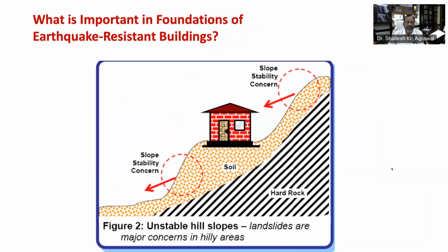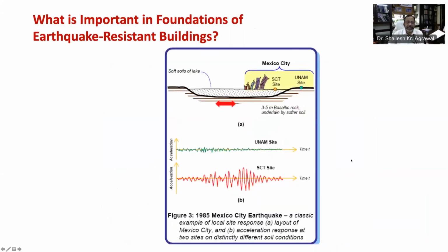When the ground shakes underneath buildings with elongated plan or long span structures such as suspension bridge, the motion at different supports may not be synchronous. Different shaking of such structures at their support induces additional effects and should be accounted for in the design. Now let's understand through this figure what is the effect of ground shaking on building.